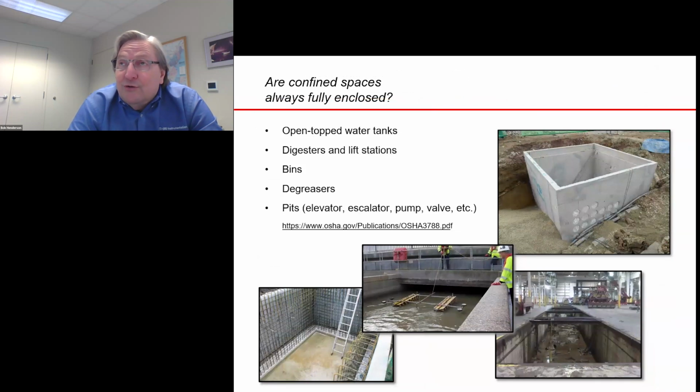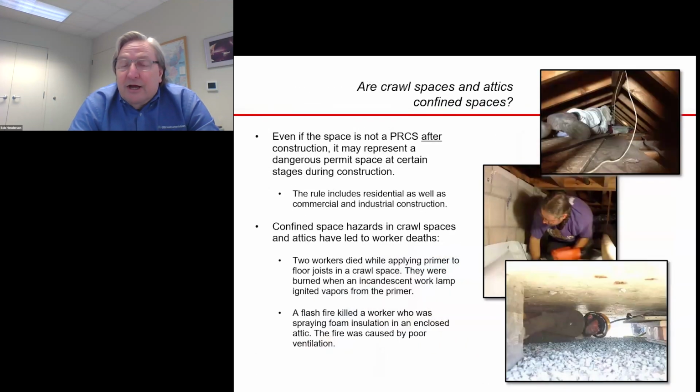And remember, you don't have to be fully enclosed for the environment to meet the confined space definition. Open-topped water tanks, digesters, lift stations, bins, degreasers, pits, excavations. These are all confined spaces. Crawl spaces and attics. This one is going to be controversial, I think, for anyone who does a lot of single home construction or building construction. Sorry, guys, it's a confined space.